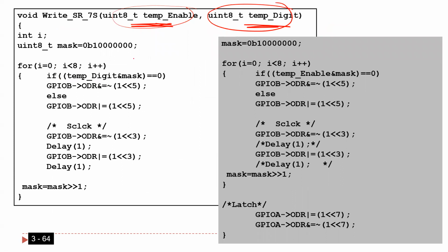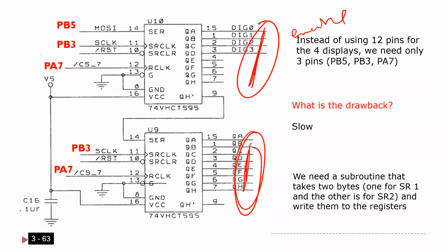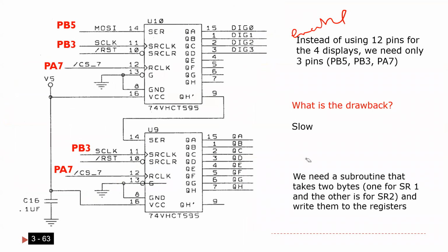So as you see here, that's exactly what I did. I made 2 for loops, similar to what we did before. In every iteration, we shift bit by bit. I have to start with this one, because the first bit you enter is this one, since every time you shift, you have to enter this one first. It has to come here first, and after I shift, it comes to here. You understand what I'm saying?